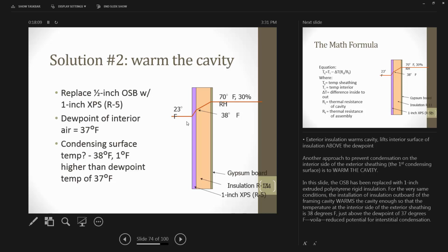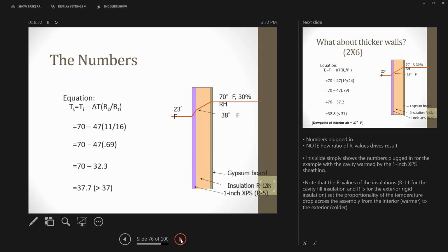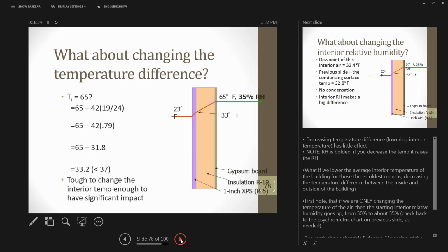We've got a wall assembly with little to no chance, at these conditions, of having moisture problems. And this is where the dew point method is starting to get pushed aside and not used as much, because it's not an absolute.